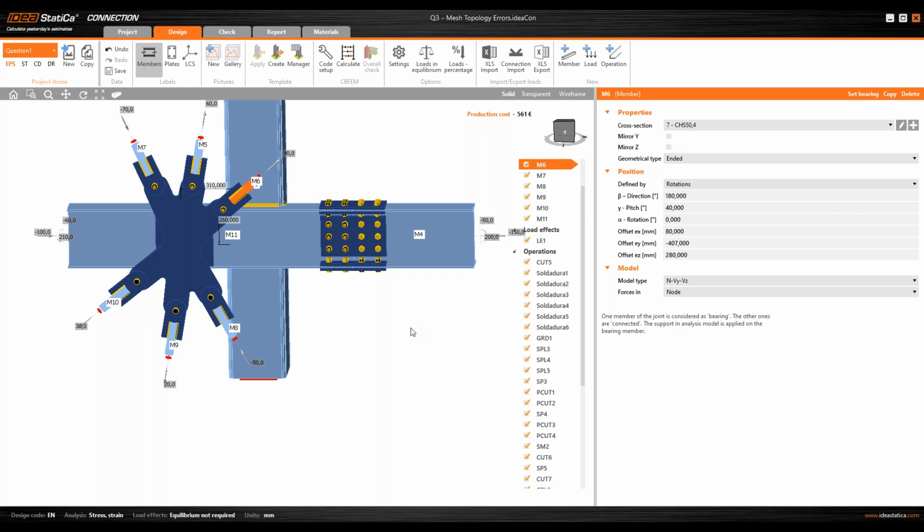And maybe, yes, I would ask one more thing. During the export or import of a plate from the DXF, users very often have some problems, some errors with that import. Can you mention the two most common reasons? Why is it so? Yes, the first comment I have during the workflow is to check the units, because this is the first problem.